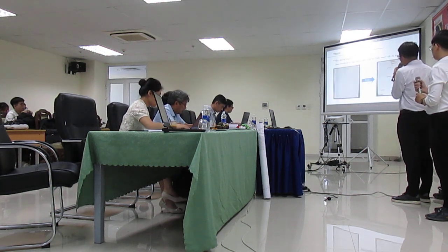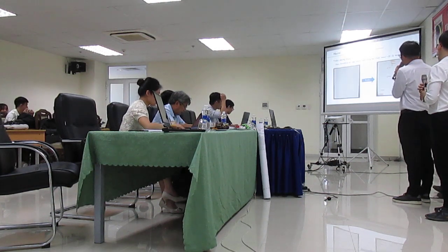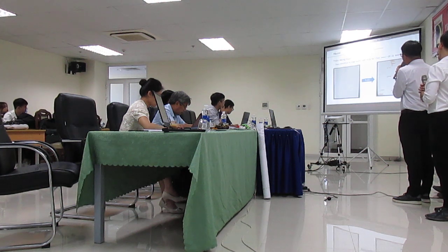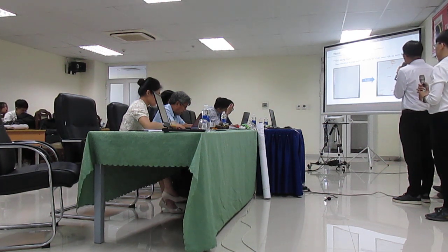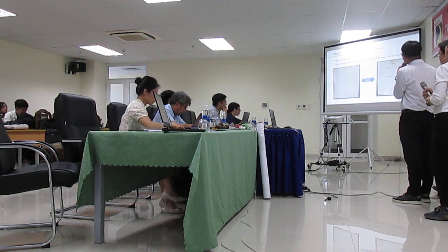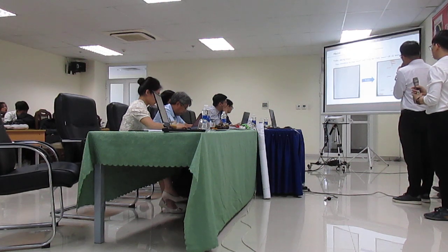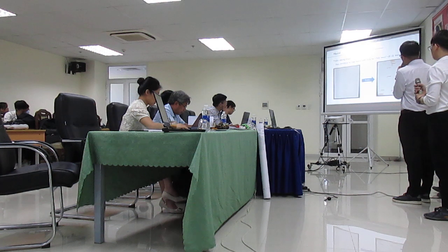And the final step is the model stack. Here we export the model and use it to predict on images. There are the parameters we use for prediction, and there is a predicted image. We can see the model can detect most defects.